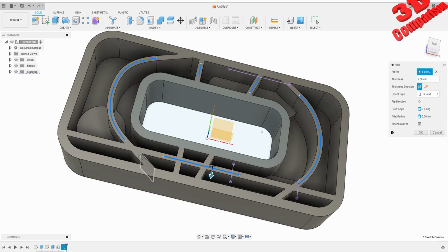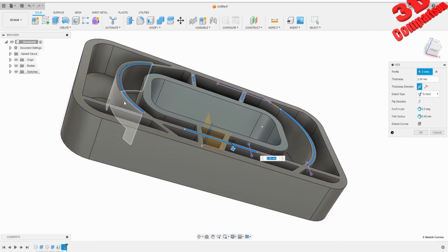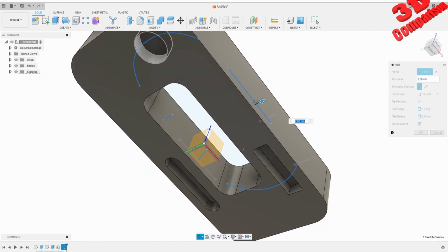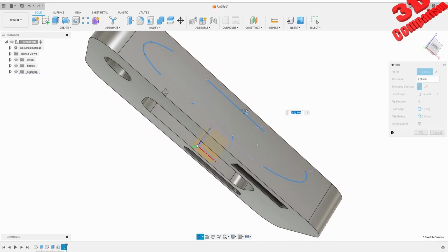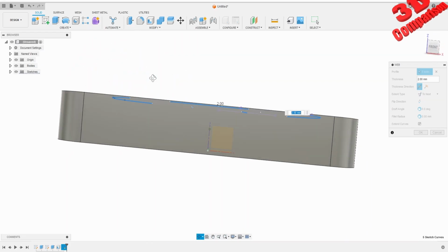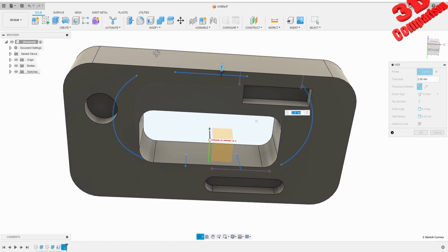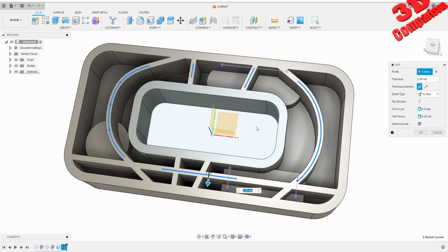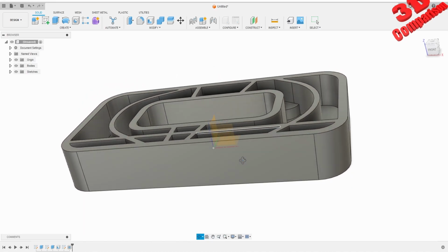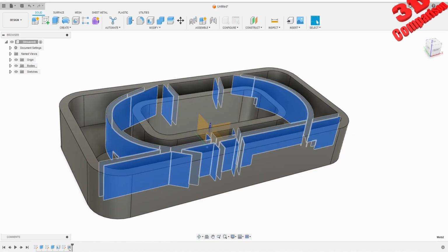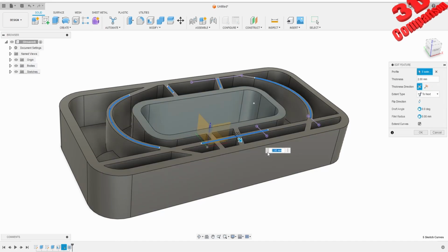And if I rotate all the way to the bottom, we see that we had that top section over here. But over here within the cutout, we won't have any material added. So this will be only added from the surface direction where they have been created. This is why I defined this profile over here with that circle. And at the end, if I click OK, we're going to see how those web profiles will be defined. If you want to edit those, we can always right click over here, edit feature, and we're going to go back over here.